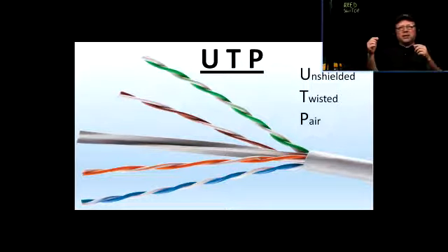And then if you have another pair beside it that is also twisted, it's not going to have enough area that is going to be equal with the other area. So the field is not going to be as susceptible to the interference from the other pair. And then on top of that, you're going to twist both wires at a different rate. So now it's another obstacle for the interference to overcome: not only are they twisted, they're also twisted at a different rate. So there's no constants, there's no regularity in that.